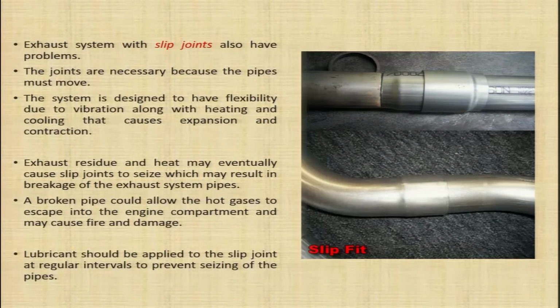A broken pipe could allow the hot gases to escape into the engine compartment and may cause fire and damage. Lubricant should be applied to the slip joints at regular intervals to prevent seizing of the pipes. So, it is very essential to apply lubricant at the slip joints.